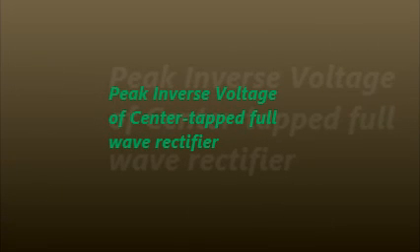Thus, the whole voltage Vs developed in the upper half of the AC supply is provided to the load resistance R load. Similar is the case of the diode D2 for the lower half of the transformer secondary.